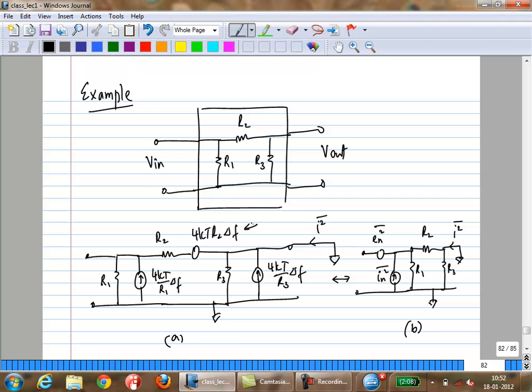That is true. But if you have negative gains in the circuit, that is not so obvious. If you take transistor-based circuits where the gains can be negative or positive through different paths, you may perfectly well have multiple paths for the noise to travel through the circuit. That is when you really have to worry about correlation normally.